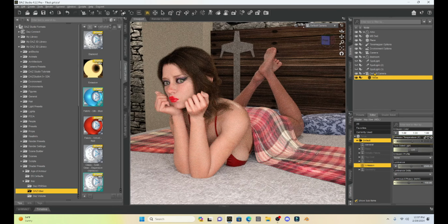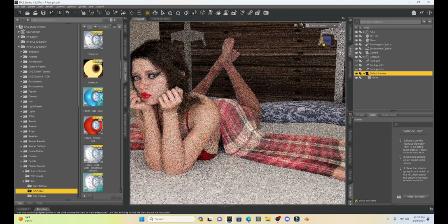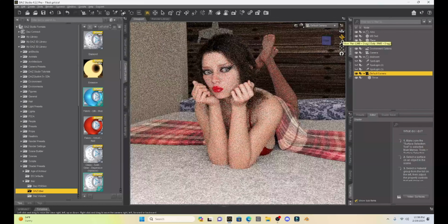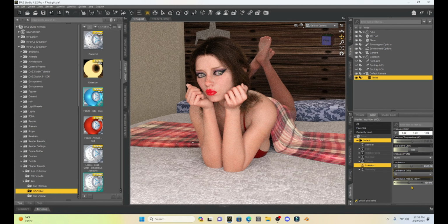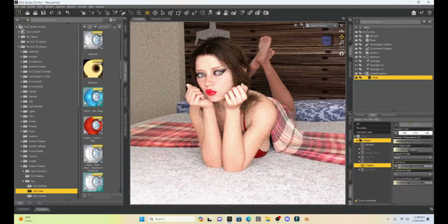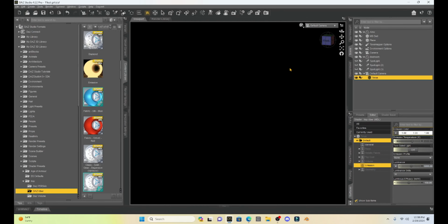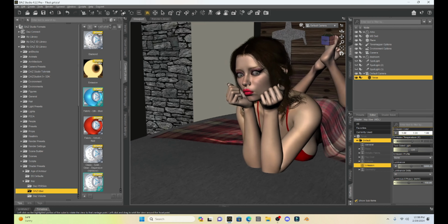And if I select that default camera, see, I can move it anywhere I want to set up my scene. Just select my Taurus, go back to emissions. Kind of like 5,000 watts. That might be a little too much for her. If I want to work in texture mode, remember, it'll be black, but I can select the scene and press Control L, and it'll make it so we can actually work in it.